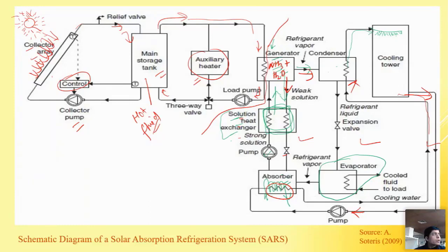Even for today, if we are talking about solar radiations, this morning there were no sun rays with this much intensity, but currently around 500 watt per meter square radiation is available in Jaipur also. So the very important thing to discuss here is that solar radiations are not so reliable everywhere. To make the system more reliable, if some day is not a sunny day, then what to do? For those cases, we need an auxiliary heater. So if the solar system does not work, the heater will work.